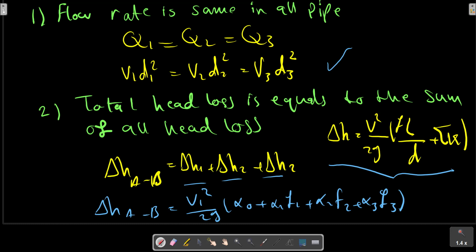If the head loss is given, a little iteration is needed since f1, f2 and f3 are dependent on V1 through the Reynolds number. Begin by calculating f1, f2 and f3 assuming fully rough flow, and the solution for V1 will converge with one or two iterations.